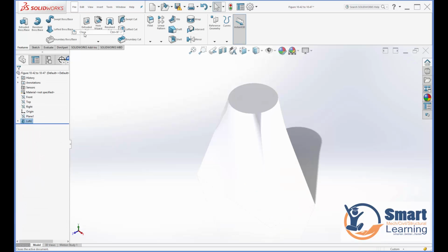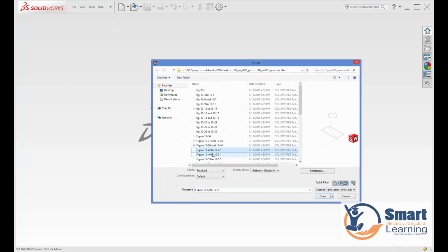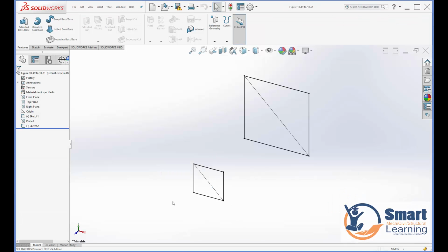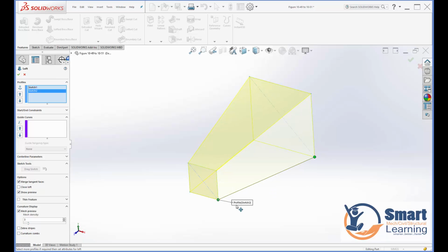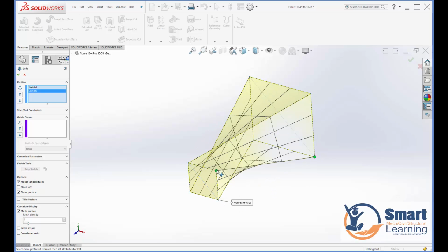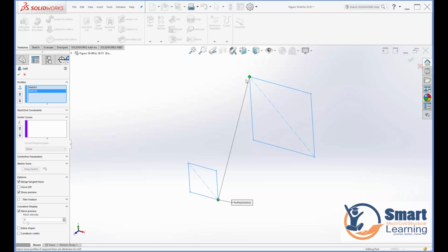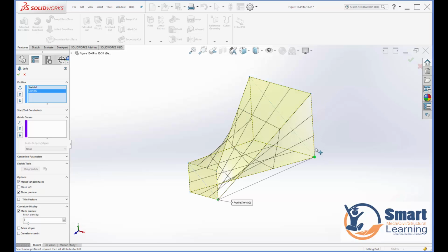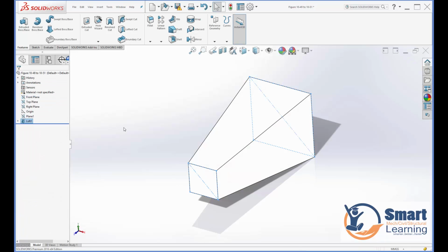And another example I would like to show you is this example, and how to use that. If you go to the loft and select your starting and ending one, here also you can see the same thing, like the twist and all. You can realign this directly. So these two green dots are nothing but the starting and ending parameters for joining, and accordingly other points will be referenced, and you can see your final output.